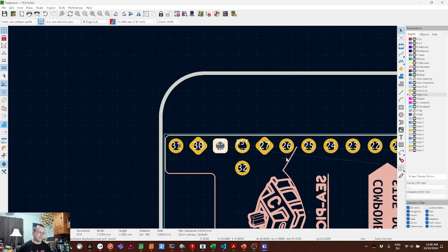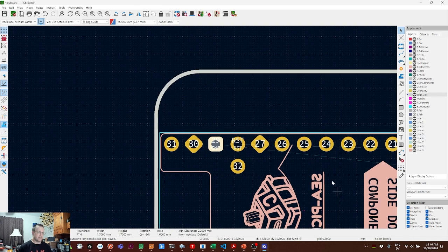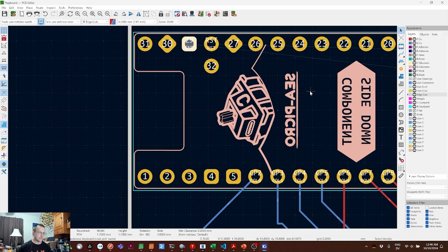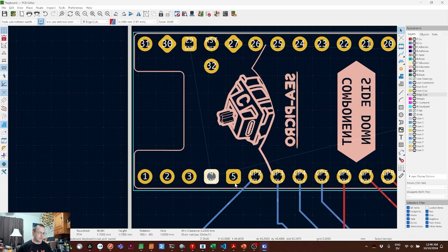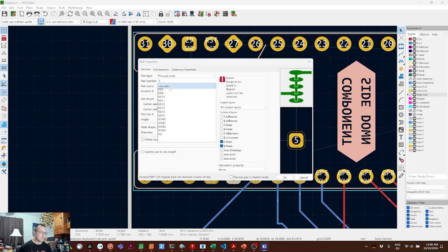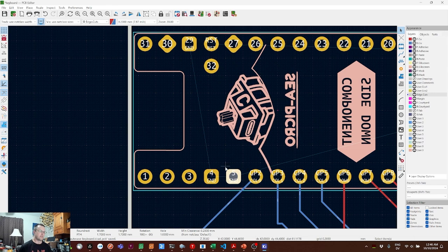We also get a rat's nest line for that, but we're going to do something a little different to connect the ground pins. While we're in here, the other 2 square pins here are also ground, and we're going to connect them all together on our board. Some microcontrollers get grumpy if you don't ground all their ground pins. Some of them are connected internally. Some of them expect you to connect them. I don't know what this one is, so we're going to connect all the ground pins.